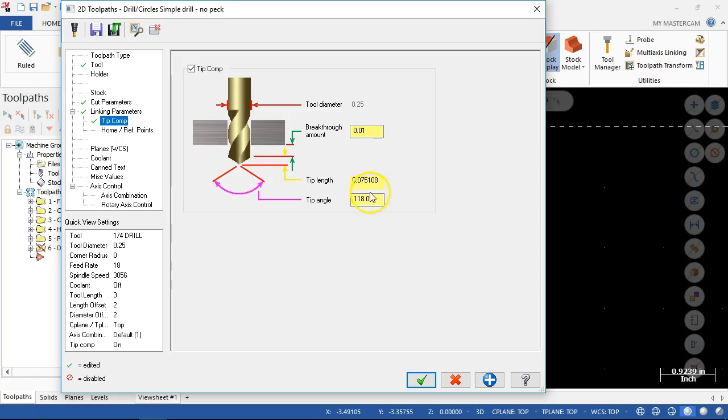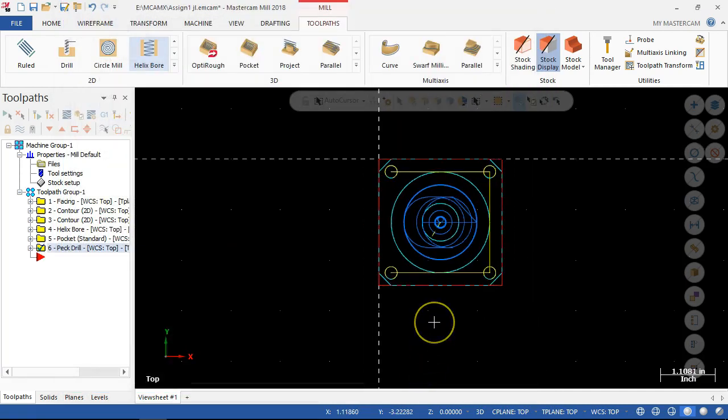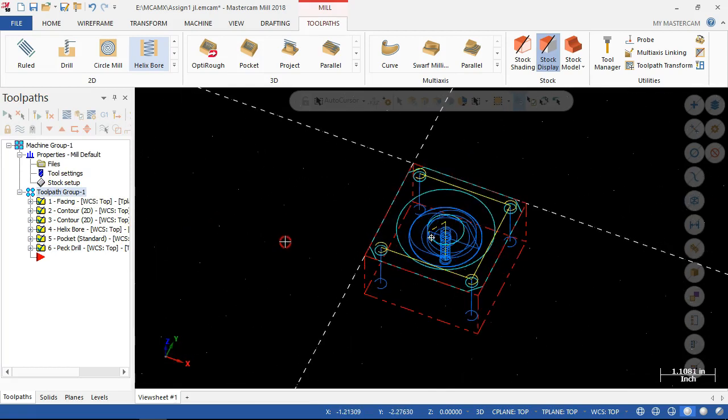All right, the other thing is this isn't going through the whole 1 1/4 inch of material. We're counting that when I flip that over and face off the backside, those holes will magically appear. All right, so we're not going to do the face operation on the backside tonight since this has run a little bit long. We do want to be able to do the simulation though, so I'm highlighting so that all of the folders are checked. When you go to the Toolpath group, it grabs everything.